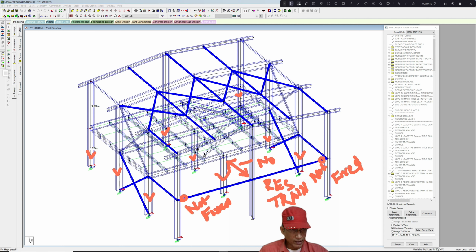But there is a restraint at the top. Through the bracing, the forces will travel to foundation. So for this column, the LZ parameter will be 1, but for the whole height. So what is our height?